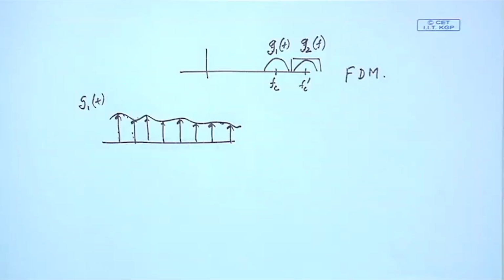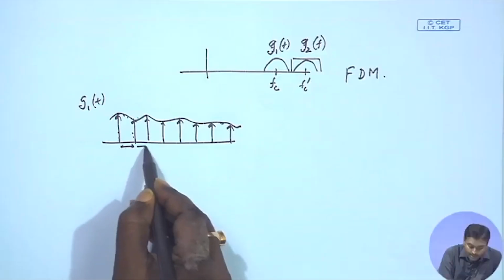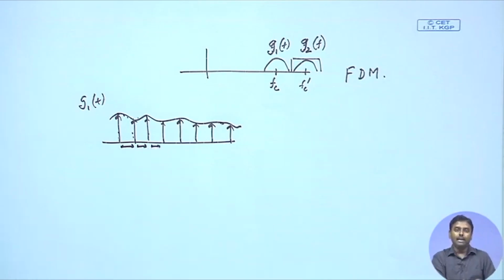This holds if the signal is band limited, as Nyquist has already pointed out. So, these samples are good enough to represent the signal. What the sampling theorem is doing is freeing up some of the time which is not being utilized for transmission of the signal. After sampling, we will be transmitting only those samples, so only a few instances of the entire timeline. The rest of the time my transmitter as well as my receiver will be idle. So, I can employ this to multiplex other signals. That is my purpose now.